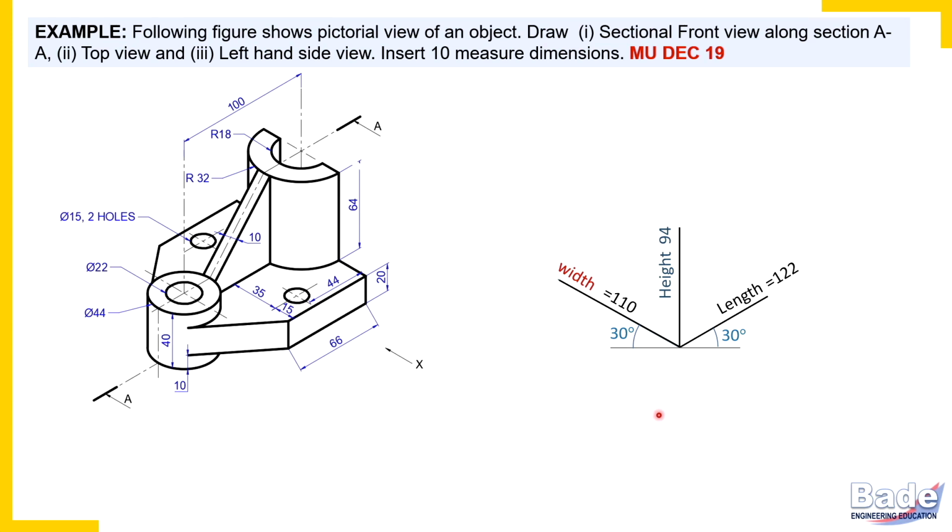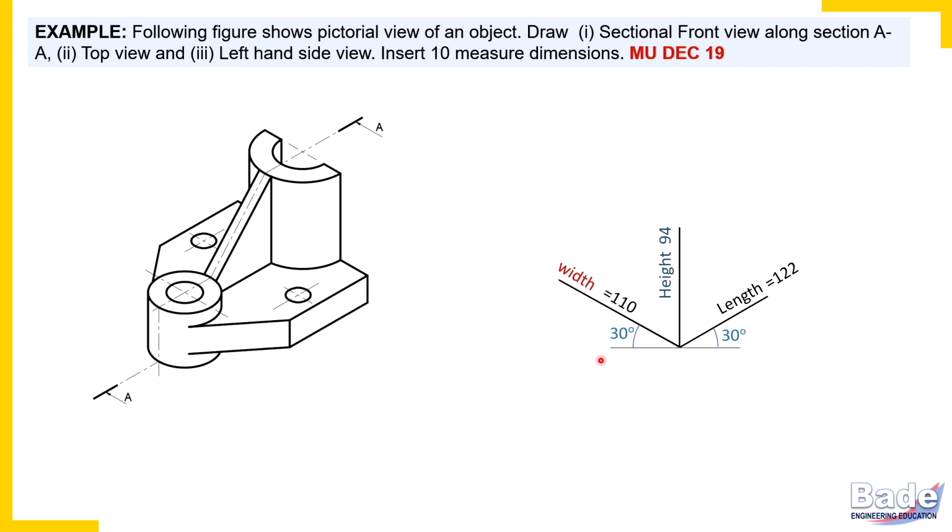It is the first angle method of projection. So the left hand side view is to be drawn on the right side of the front view. So when you draw, at the initial stages, the three rectangles for the front view, top view and left side view, be careful that there must be enough space on the right side of the front view. And we should start with the front view rectangle, that is, take care of the length axis and height axis. Okay. Now the side view of the complete object, the top view of the complete object, and check here.